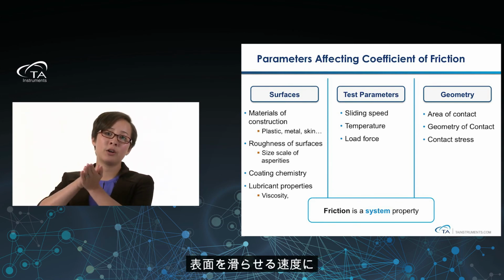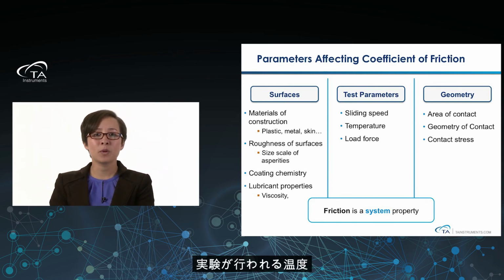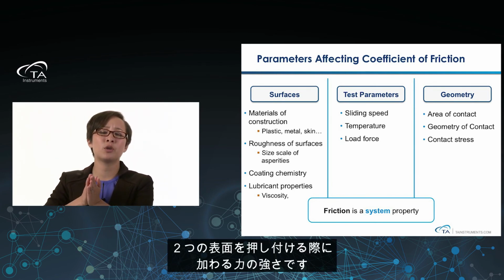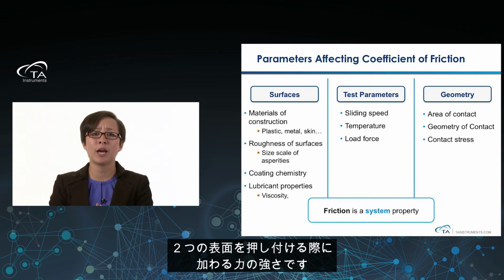Now when we talk about the test parameters, we can define things such as the sliding speed, so how quickly are our surfaces sliding past one another, what temperature is this test being performed at, and then what's the load force, so how much force are we applying when we push these two surfaces together.